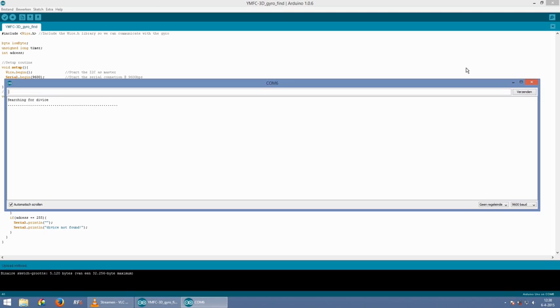This program checks every address of the I2C bus to see if the gyro responds to the Who Am I request. When the gyro responds, it will show the type and address of the gyro on the serial output. In case the gyro does not respond, a failure message will appear. If this happens, you need to check if the gyro is correctly connected to the Arduino Uno.